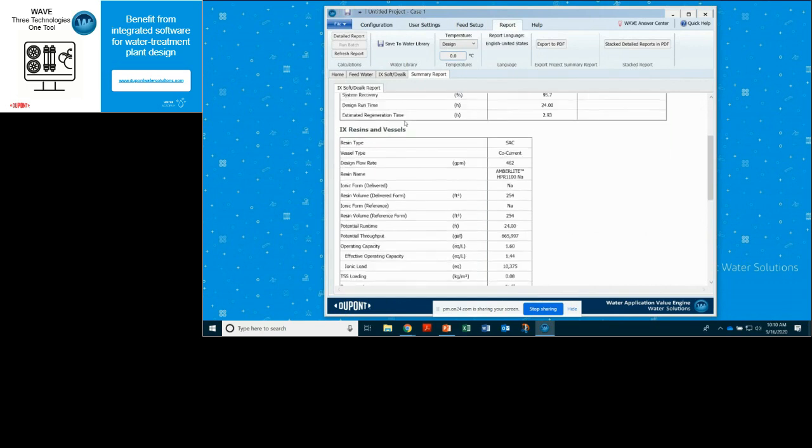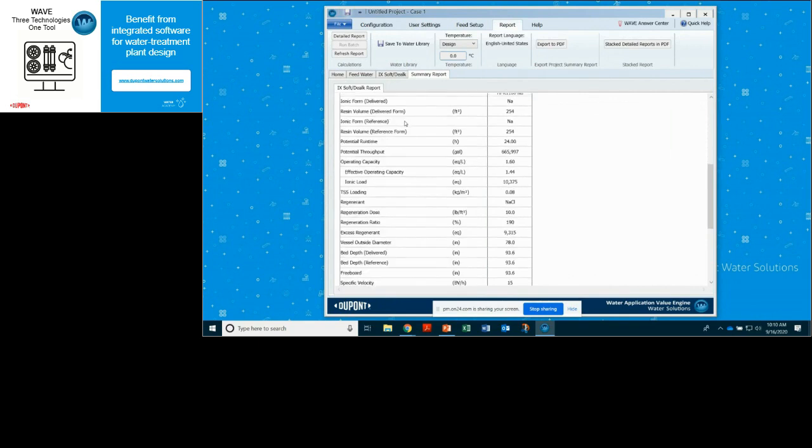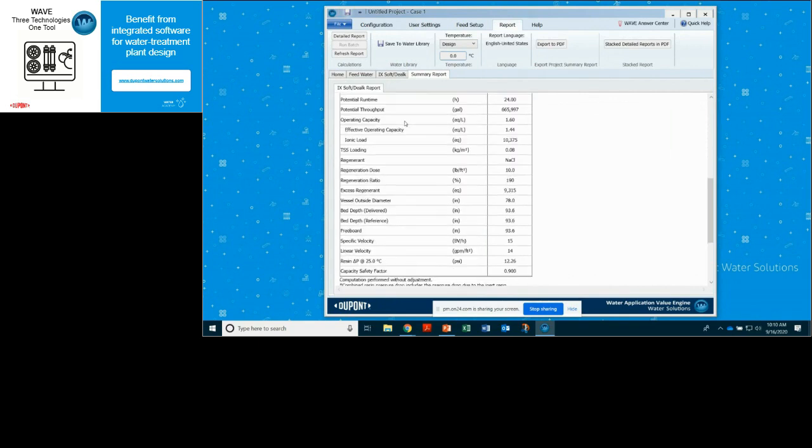And then do you mind scrolling down, Garth, just to look at pressure drop? One of the things that we had noted from this design, and I think this is where we're going to get into one of our first deeper features, is that there's a stipulation that across the full feed water temperature range, we would not exceed a pressure drop of 20 psi. And in this case, if you don't mind just pulling your mouse down there, at the design case, we're seeing a pressure drop of about 12.3.